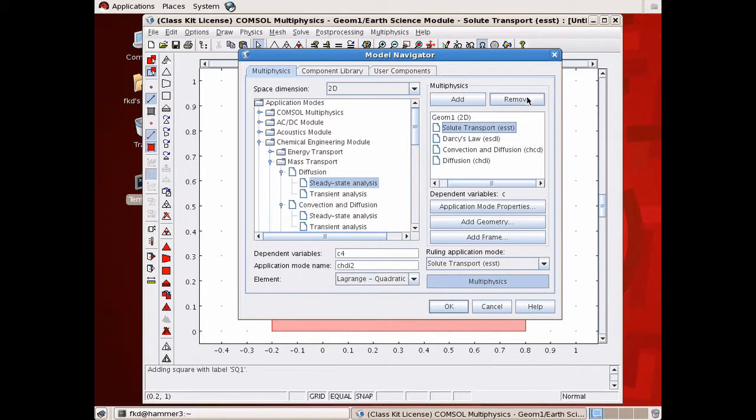So I'm going to get rid of these. We could keep them there, but I'm just going to get rid of them because it makes it complicated. And so I'm going to remember the fact that this is concentration. Actually, the other thing you'll see, if for instance, we added another one of these, you'll see that this marker here has this suffix 2, and these are the magnitudes of the concentrations that are the dependent variables in these equations. And so it indexes the dependent variables that it will solve.